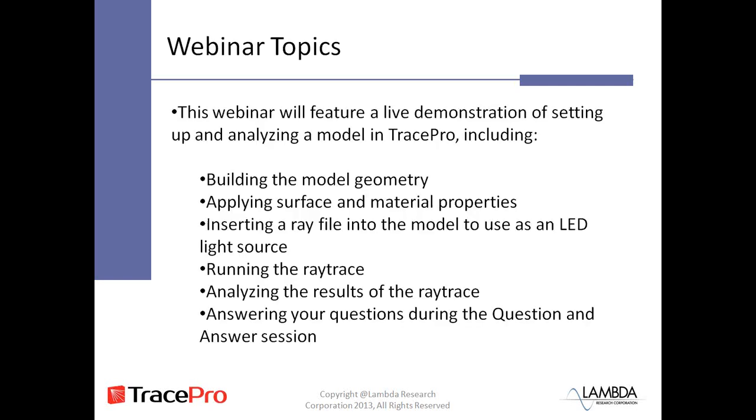So the topics of today's webinar, as I just mentioned, will feature a live demonstration of setting up and analyzing a model in TracePro, including building the geometry. In this case, I'll show importing geometry from another model, as well as building geometry within TracePro itself, applying surface and material properties, inserting a ray file into the model to use as an LED light source. Fairly often we get asked, how do you use ray files in TracePro? So we'll be able to show that in this webinar. Then we'll show running the ray trace, and lastly, we'll analyze the results. And then we'll wrap it all up with the question and answer session.